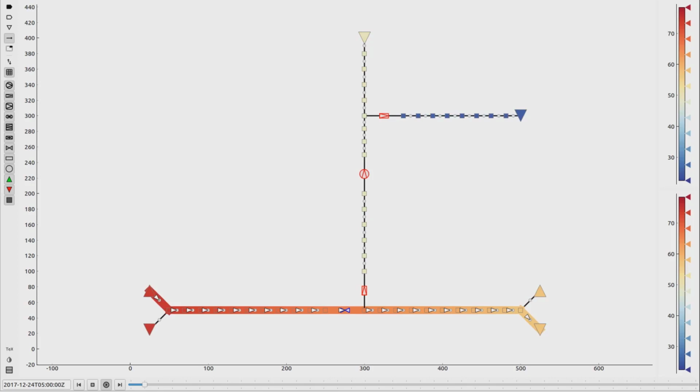Remember that valves have the same pressure level at both sides of the element in case they are active. Compressors increase the pressure, so the pressure in front of the element is lower than the pressure after the element, and regulators decrease the pressure in flow direction, so the relation here is the direct opposite.